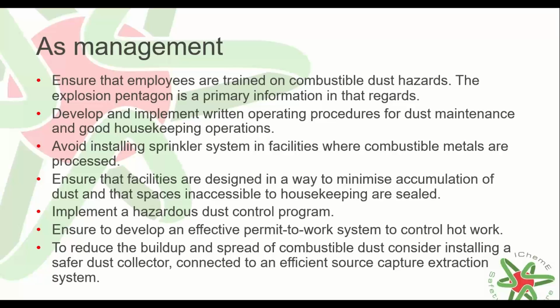The explosion pentagon is a primary information in that regard, and I would like to highlight this because in some cases it may be that we tend to forget about the pentagon, but that is a basic information here and really important. In addition to that, develop and implement written operating procedures for dust maintenance and good housekeeping operations.